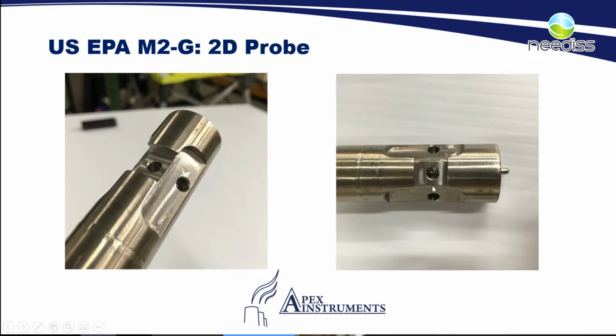Now, I want to make it clear that the EPA does not allow the use of 2D or 3D probe heads in conjunction with, or to be used with, an isokinetic nozzle when you're doing isokinetic sampling. If you do have such turbulent flow and you want a more accurate flow rate, you would perform your method 2G or 2F using this equipment in your setup process.